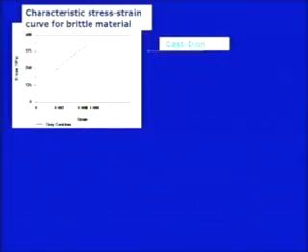Cast iron, which has more carbon percentage, always offers the damping property. That means it is always good in the compression region. That is why foundations are always provided with cast iron. So, what is the important nature? They are always good under compressive strength, while mild steel, or we can say the ductile material, is always good in tensile strength. Cast iron also falls under the category of brittle material; it has brittleness, meaning it is not good under tensile load, it is always good under compressive load.